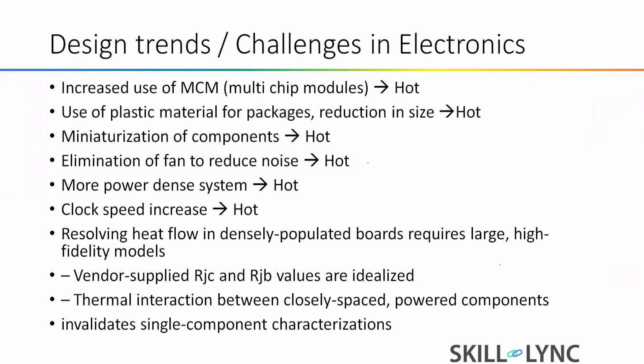Again, we have to consider the thermal interaction between closely spaced powered components. As I told, on a single PCB board we have different multi-chip modules, which again becomes very difficult from two points of view: one is the electrical point of view, and the other is the thermal point of view. Both require spacing, and then we have to design the PCB as well. So these are the trends in electronics design which pose the challenge in thermal analysis.